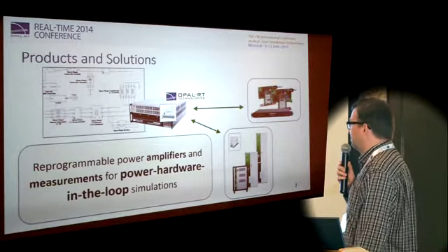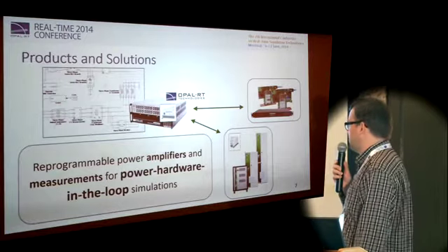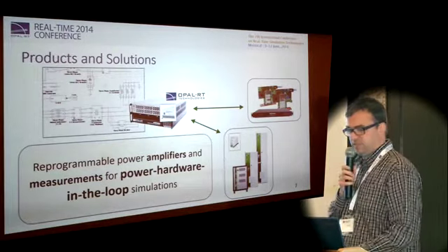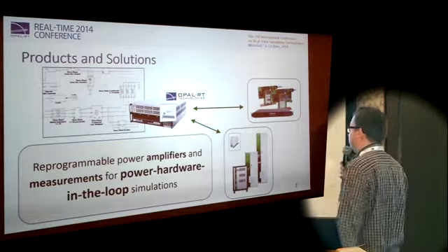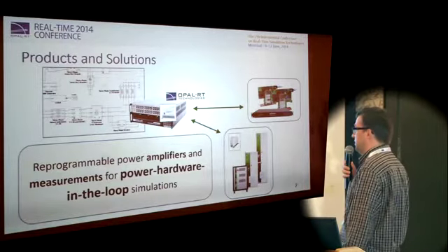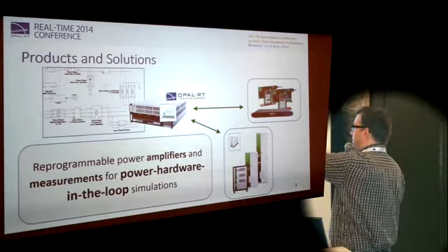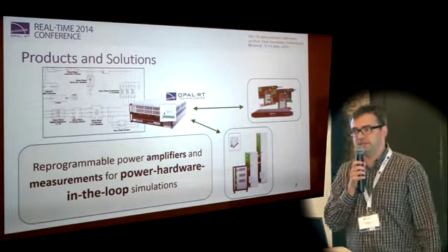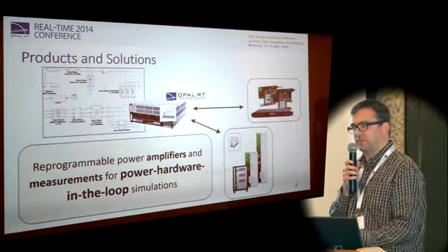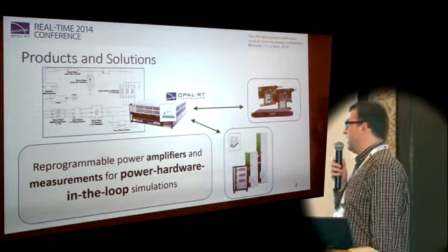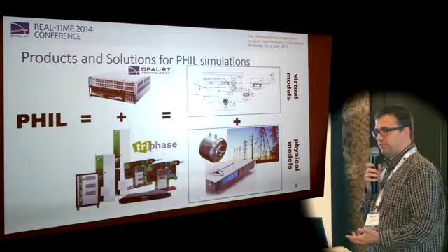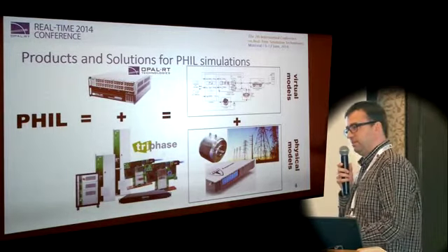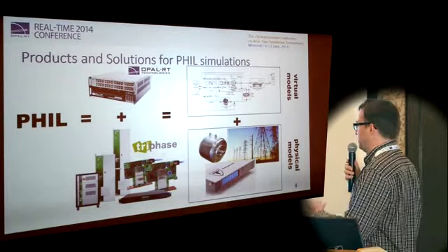And you can connect it to a powerful simulation unit like the ones that OPAL-RT is providing. So this gives you a very powerful solution for power hardware in the loop simulations, whereby a major part of the system that you want to simulate is going to be virtual, not physically present, entirely in the mind of the computer. And then the three-phase measurements and actuators help you interface with reality, with the device under test, which is physically present.